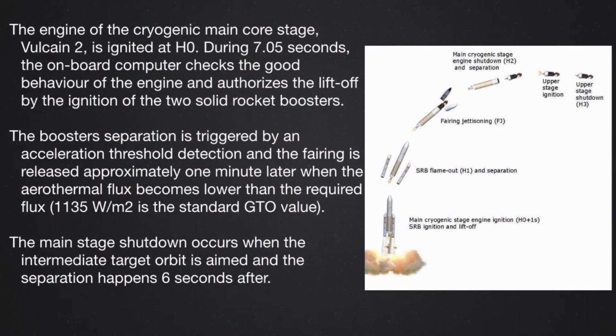Okay? What happens at takeoff is that you know the difference between a liquid engine and a solid propellant engine: a solid propellant engine, you cannot shut it down. Once it's switched on, it goes until the propellant is over. The liquid engine, whether cryogenic or storable propellant, you can shut off because you just need to close the valve that feeds the combustion chamber and the engine stops working.